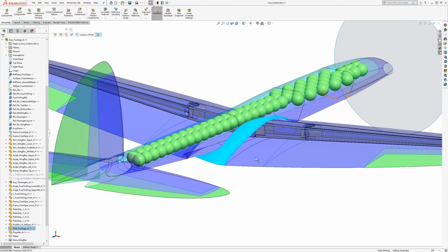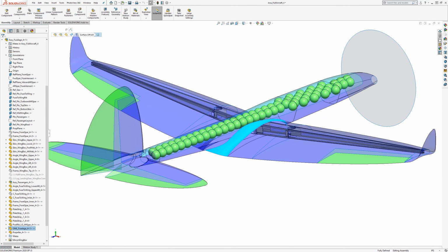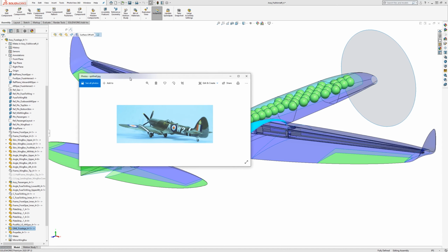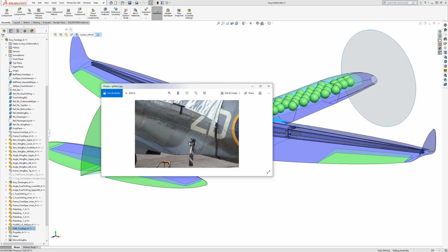Now, I'm not an aerodynamicist, so I can't give advice for which type of fairing to go for on a given aircraft, but we can look at other designs that are established out there. For this one here, what I was emulating was the one found on the Spitfire, so that's a small radius towards the leading edge and then the radius gets larger and larger towards the trailing edge. And it is a low wing, so the trailing edge is a bit lower than the fuselage, and they loft the trailing edge back out to the fuselage.